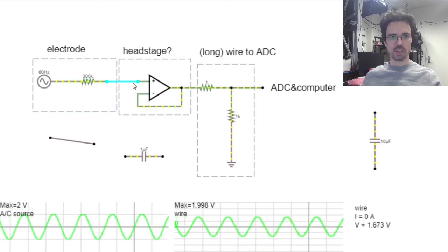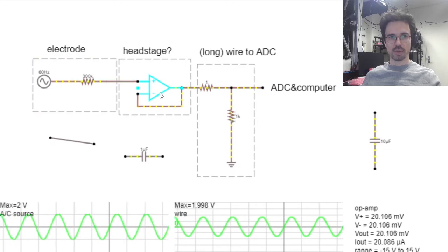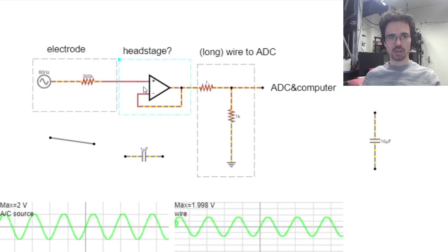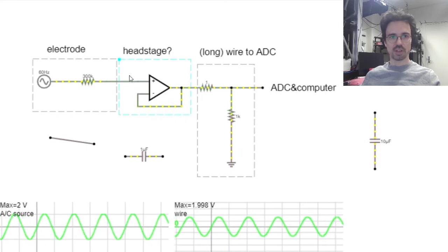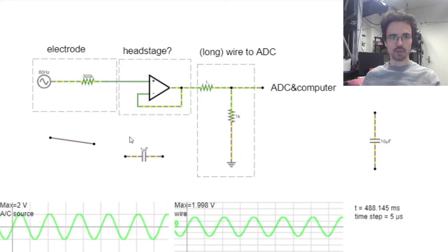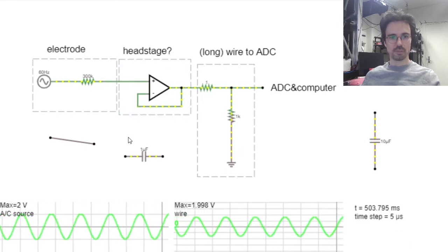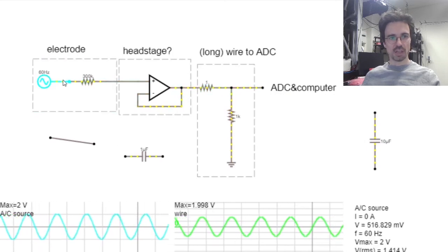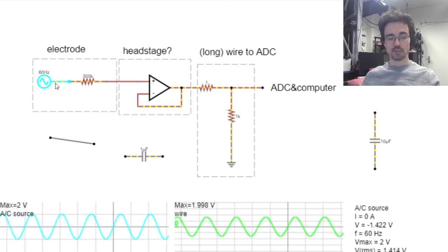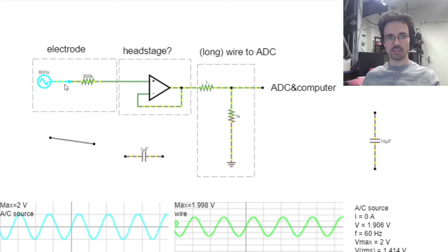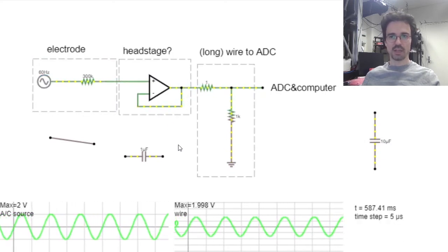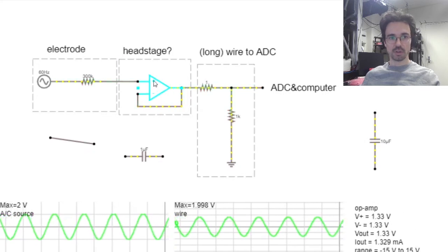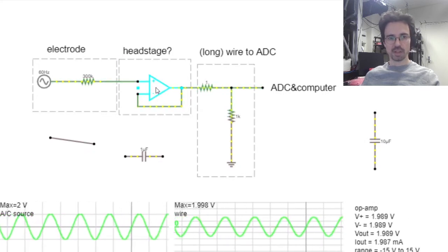And we're doing this by putting a non-inverting op-amp here, which, as we talked about, doesn't take any current into its input, but yet has the ability to provide the same voltage. So one way to talk about this in the language of impedance is that we have a high output impedance source, which is our tetrode in this case, and we have coupled that to a very high input impedance input on the head stage, on the buffer amplifier.